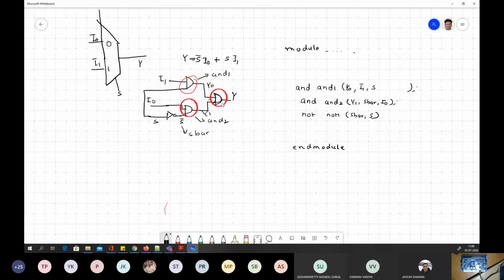So now similarly what we need to have is this OR gate, right? So this OR, of course. Verilog is, let's say, case sensitive, so we should be really careful. Okay, this is my OR case instance name. Okay, y is my output. Yes, capital Y is your output. Okay, then your y0 and y1 are input.